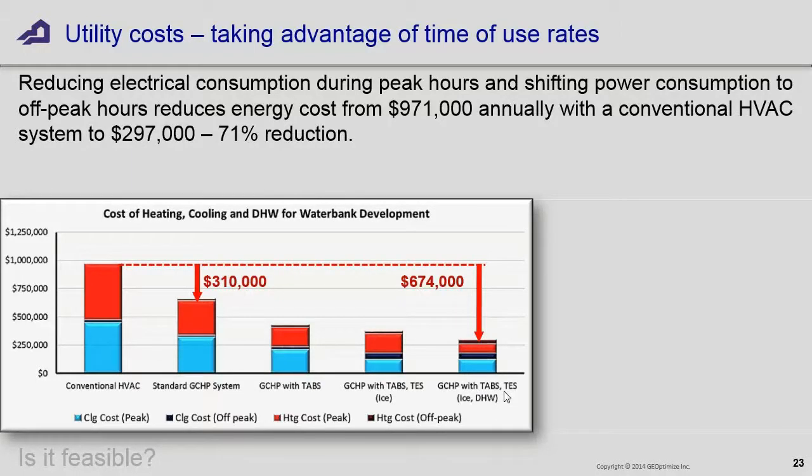This was done on a feasibility study basis, and I talked to a lot of people at Uponor, and they've done a lot of systems like that here. I talked to a guy out of Germany for quite a bit, and what they've been finding is that they reduce the peak loads by about 15 to 30%, even more. This was modeled at about a 20% saving.